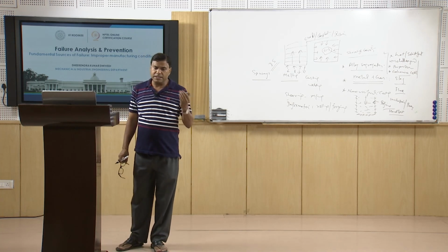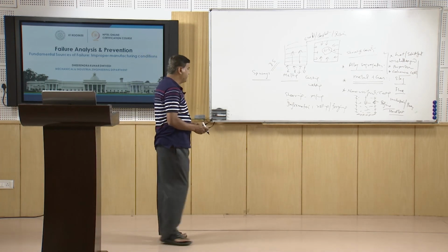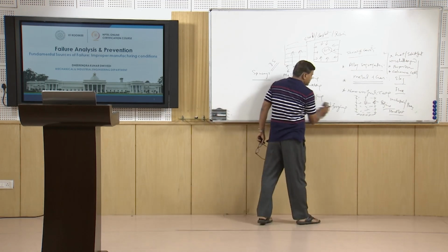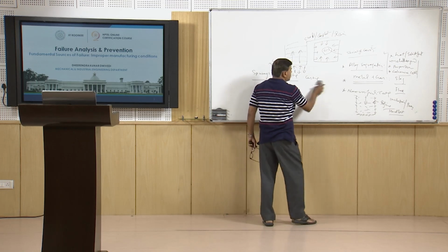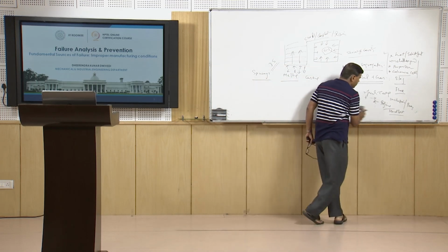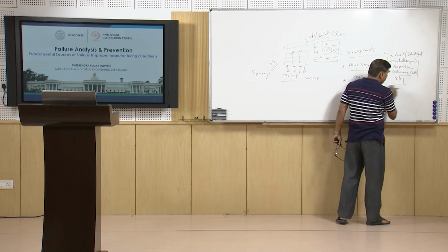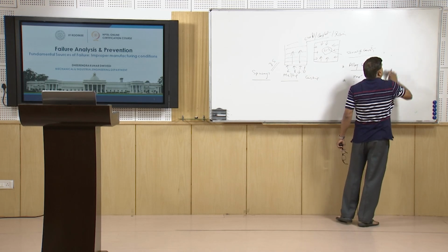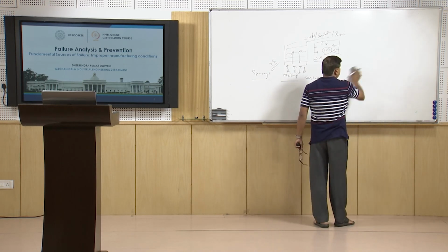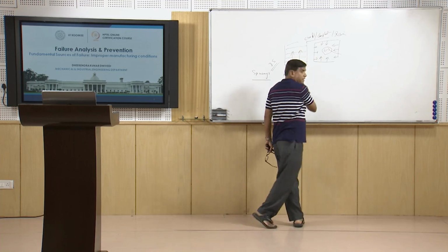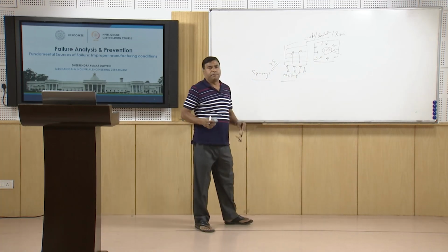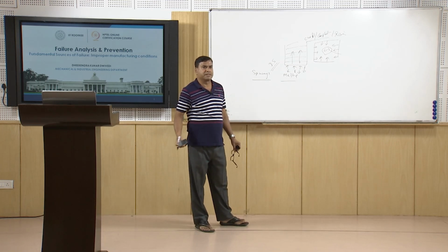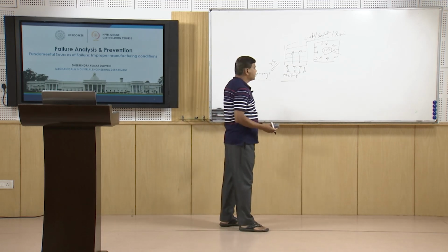It is easy to recognize whether the product has been made by casting or not. So, all the cast products will show the dendritic structure. This is a typical structure which shows somewhat poor mechanical properties as compared to the products made by other approaches. So, the cast structure is one typical feature which is observed in castings. Apart from that, castings comparatively show poor hardness, strength, toughness and ductility, and there is also an increased tendency